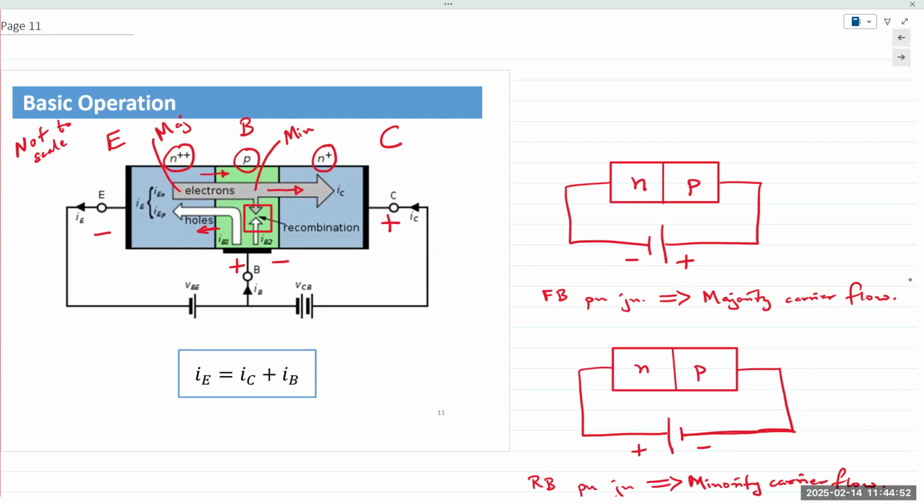But the moment we apply a reverse bias to the collector base junction, these charge carriers that are now freely present in the base, minority charge carriers, because of the reverse bias, cross over the junction, are attracted by the positive end of that externally applied voltage, and are pulled through into the collector. And a heavy current flow results.